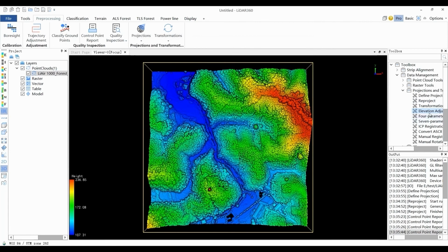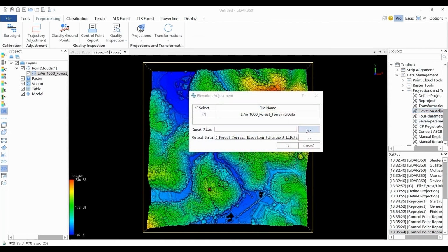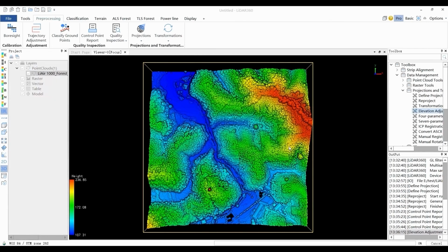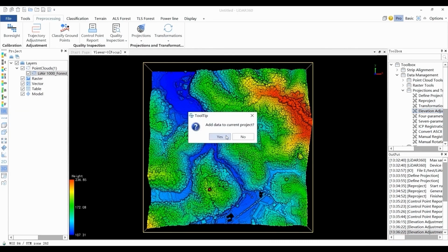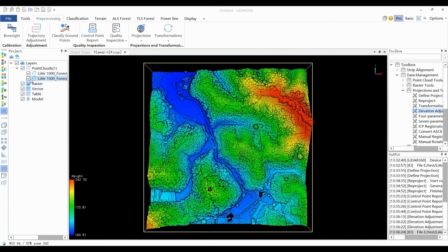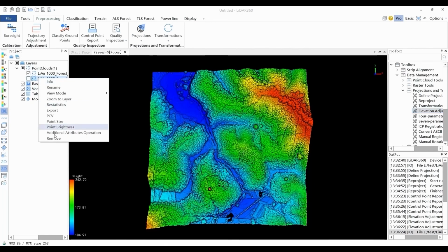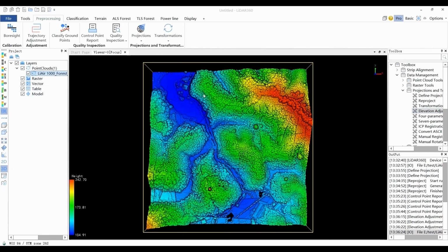For large area, the adjustment of elevation cannot be defined as a mathematical formula. Hence, the model of elevation adjustment is required to be defined. The algorithm is used to build triangular network model using known control point data, as well as to interpolate and correct local points using height anomaly between different height systems. Adjusted elevation results can be checked accordingly to the control point report.